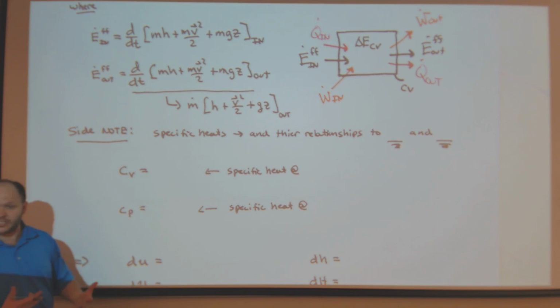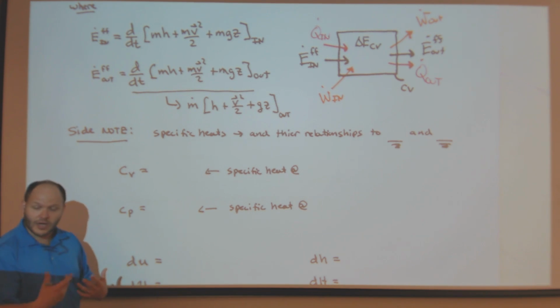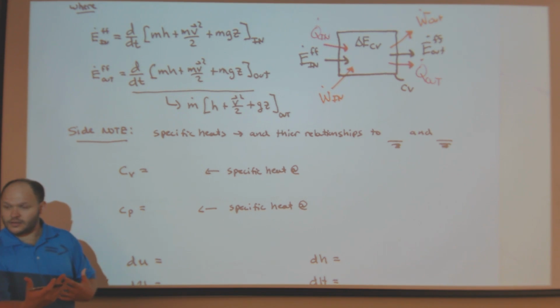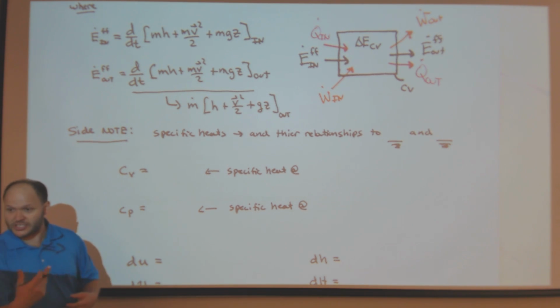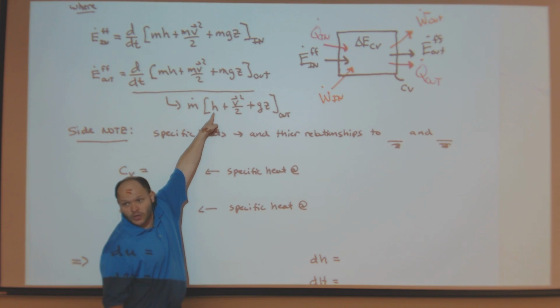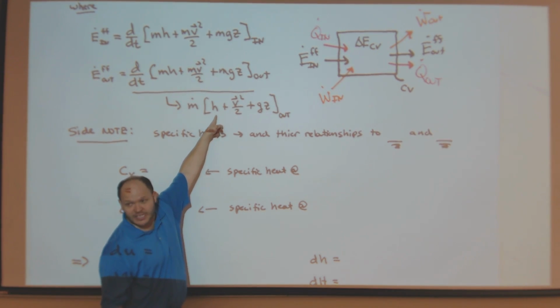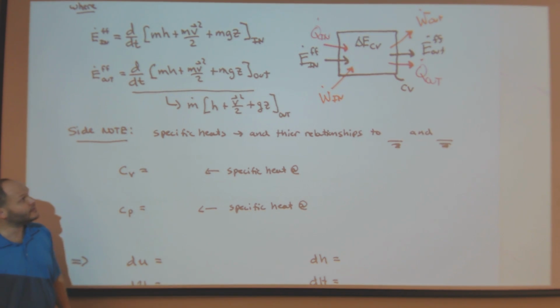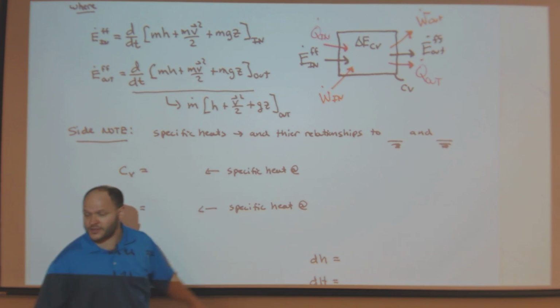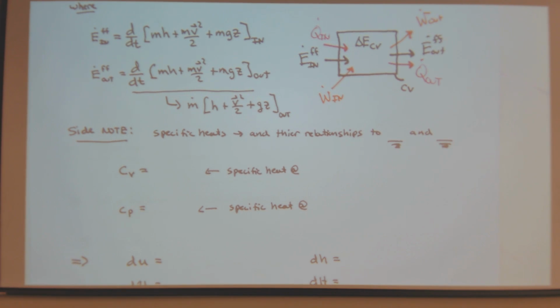Now if the temperature is changing, so if I have an unsteady process, the temperature of my mass out might be changing in time. Then this is no longer a constant, and I need m dot h plus m times h dot in there. The velocity might still be the same, but if I had some temperature dependent process, my reaction stopped working, or I had some extra heat generation, right?